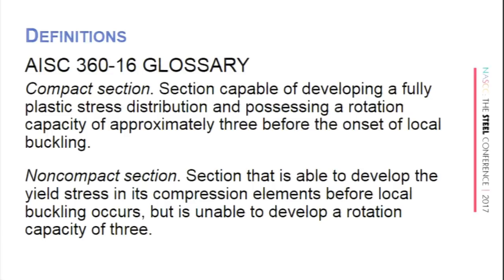And where do you need rotation capacity? Do you need it in a statically loaded structure? You need it in a structure that you're doing seismic design, right? So really, this was meant for when my beam is undergoing cyclic movement, okay, during an earthquake. That's where you need that rotation capacity of 3, not monotonically, okay? So now what we've done is we did the monotonic test, and now we want to compare the same beam design monotonically to the beam design cyclically. And where are we at?